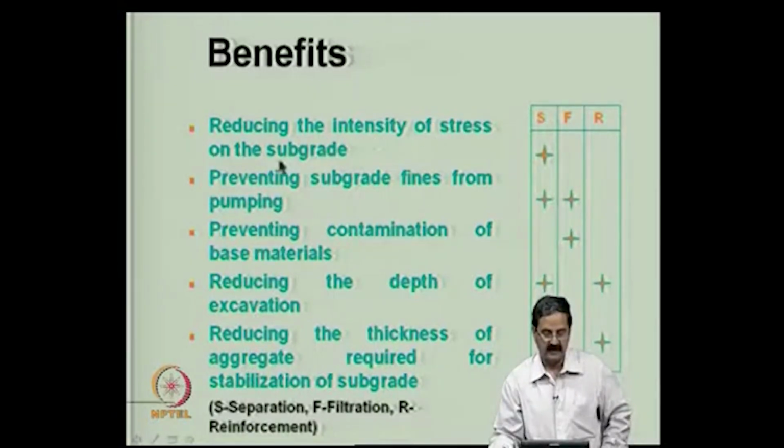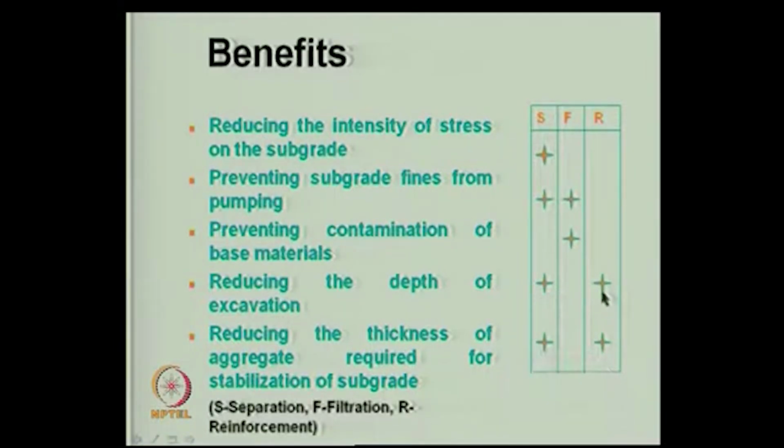Reducing the intensity of the stress on the subgrade, the separator function helps. Preventing the subgrade fines from pumping, both separation and filtration help. Preventing contamination of base materials, filtration helps. Reducing the depth of excavation, yes, separation helps, and reinforcement also helps. Reducing the thickness of the aggregate required for stabilization of subgrade, separation and reinforcement help.